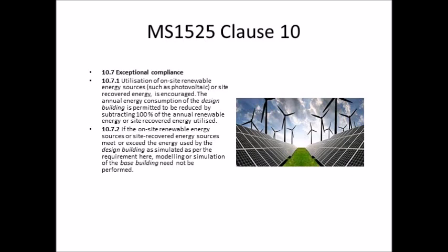So now, if you can generate this 20 kilowatt hour per square meter per year by renewable energy using photovoltaics or wind turbine, then you can subtract. 120 minus 20, you get 100 kilowatt hour per square meter per year, and that matches the performance of the base building, so you are okay. So that's what it does, to encourage the use of renewable energy on site.